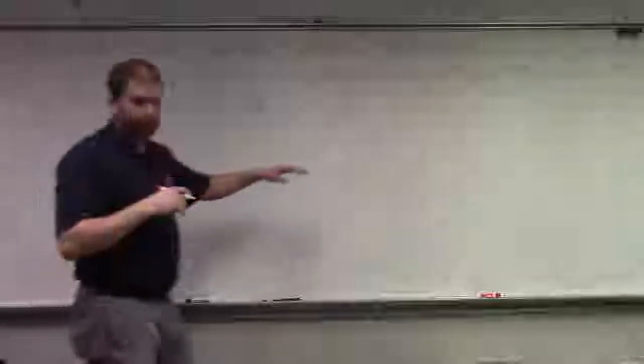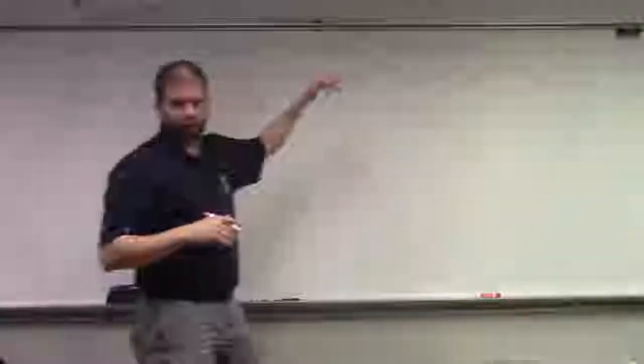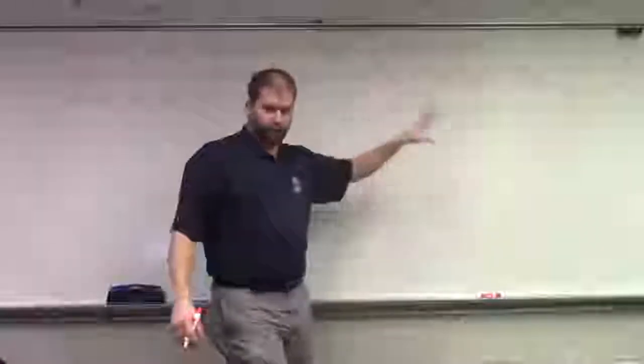Okay. The next step, we use M sub U to determine M sub T, right? The moment of our tension arm. And hey Ben. Yes, sir. So the M sub U, the 1.2 dead load and the 1.6 live, never changes. The 1.2 and the 1.6, it's always going to be that. Correct. Yep. So this is the loading condition equation for flexure.